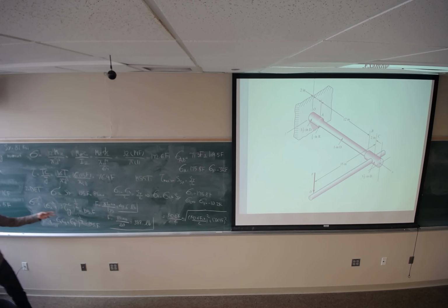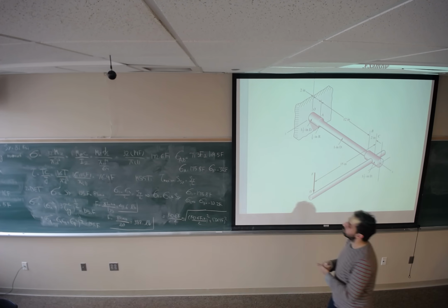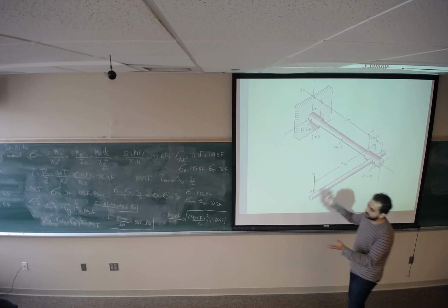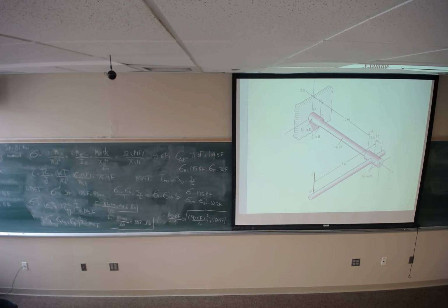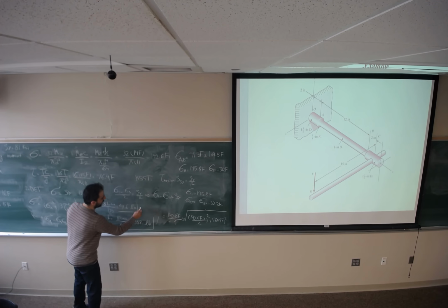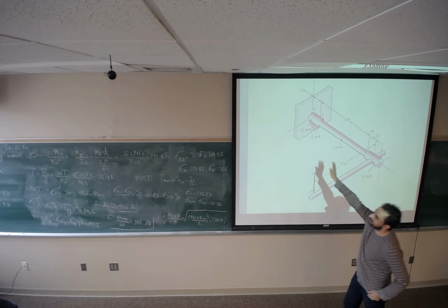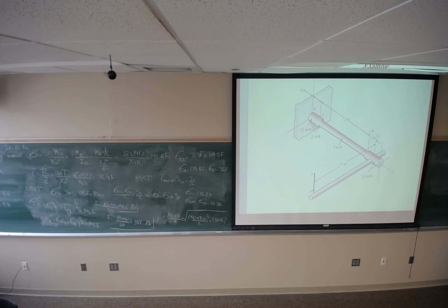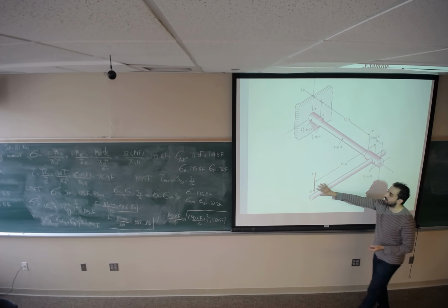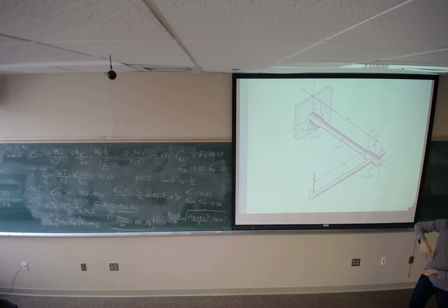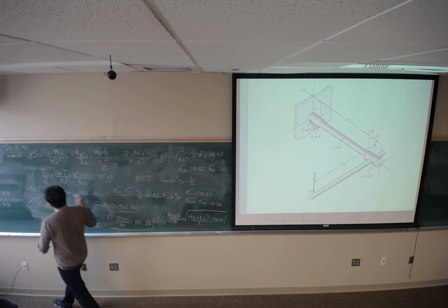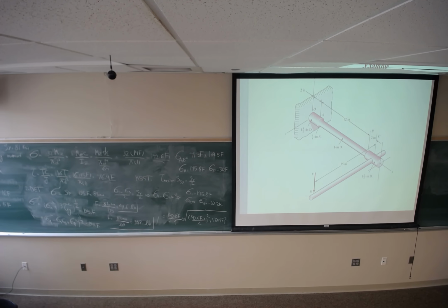So there is no right or wrong answer for this problem. If you want to be more conservative in your analysis, you shouldn't apply any force greater than 388. If you want to be less conservative, you can apply up to 416 pounds. Makes sense? So again, as you see, the first step is to find the critical section, finding all loads applied to that and then the stresses applied to that critical section, and then apply the failure theories corresponding to that material.